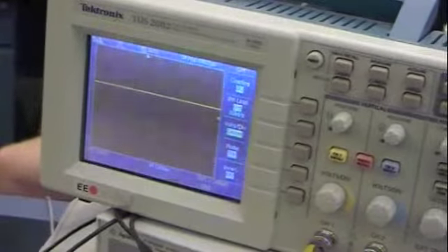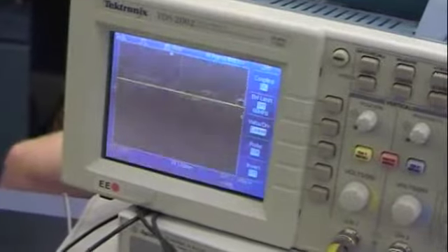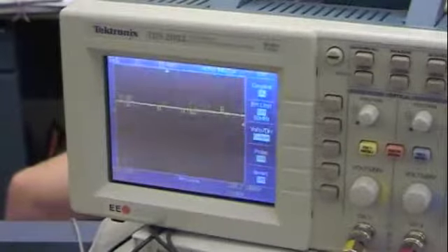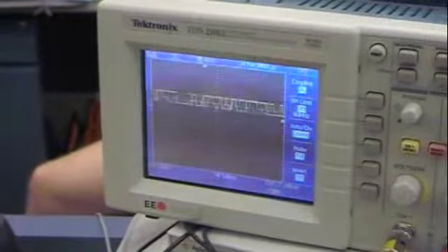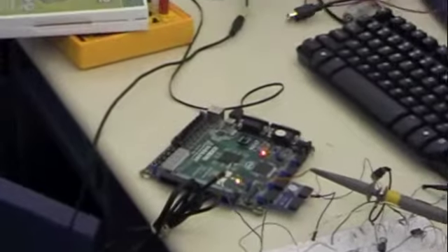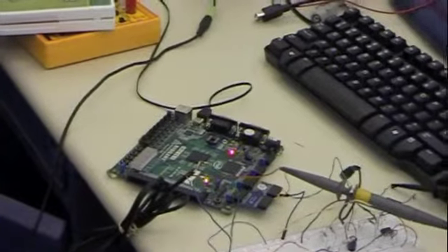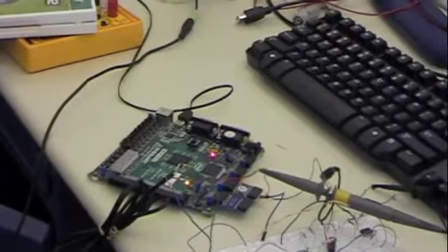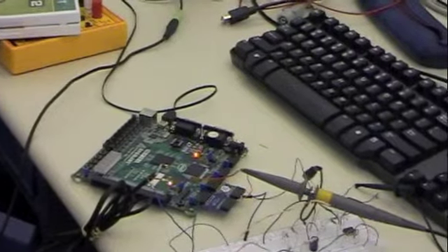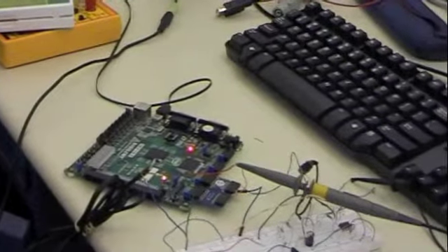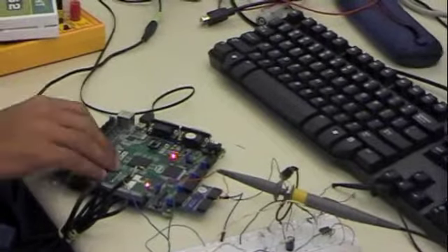Then if we go a little more, it sounds more and more rock and roll-ish. It has a lot of noise in it right now because with the addition of new harmonics, there'll be stuff way beyond 20 kilohertz, which we don't want. A lot of fuzz. So it would be ideal for a bandpass filter to be in there. And then we can go a little more, make it really raspy.